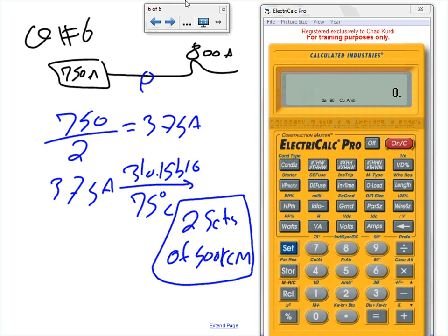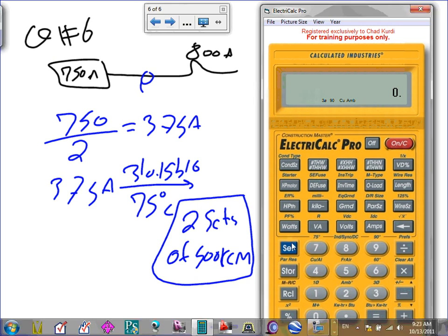If you use the calculator, guys, look at that one. Let's change my ambient temperature, it's screwed up here. Let's clear all. Set it up back. Okay, I'm going to set my conductors for 75, three-phase, perfect. So what's the size? I'm going to size based on the amps. What's my amps? My amp is 750.